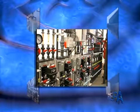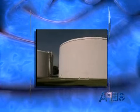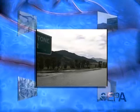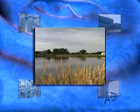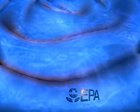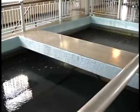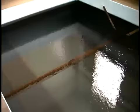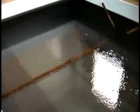For the arsenic rule, EPA evaluated several technologies as candidates for best available technology for arsenic removal, including modified coagulation filtration. Typically, coagulation filtration treatment uses the process of particle destabilization to remove colloidal and suspended matter from the water supply. This process results in the formation of floc particles that are removed by clarification and/or filtration.